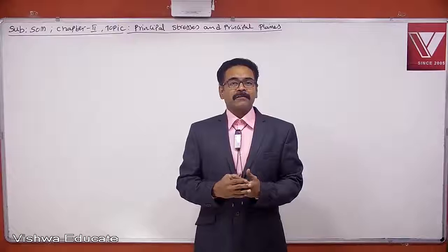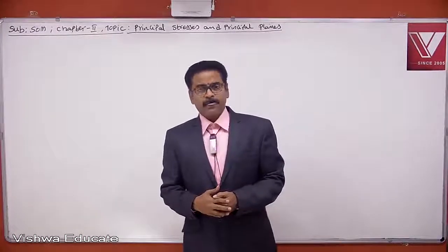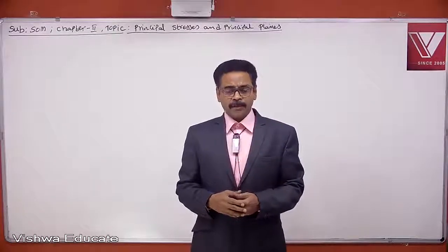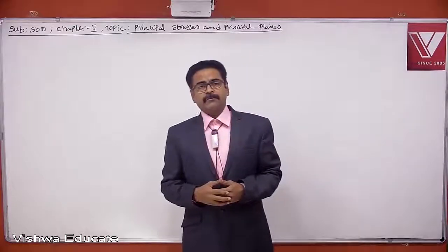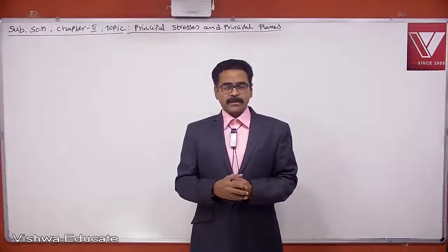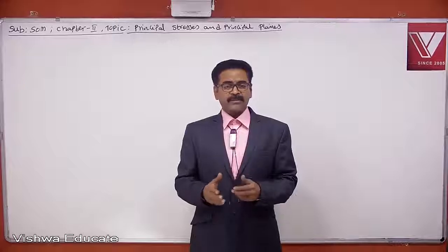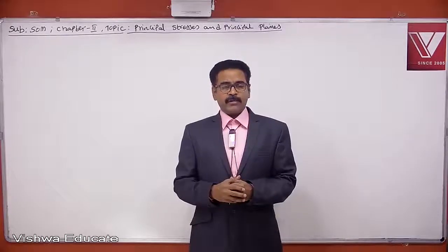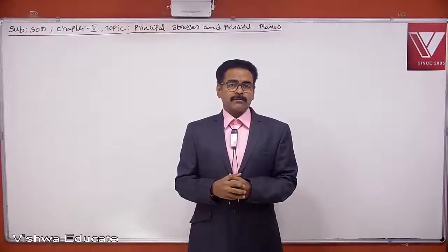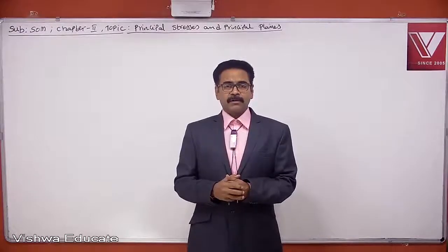Welcome back to another session of Strength of Materials. In this session, we are going to deal with principal stresses and principal planes. First we derive the formula for principal planes and the formula for principal stresses. Thereafter, we are going to derive a formula for maximum shear and a formula for shear planes. In this way, we move, right? So first let us try to derive a formula for major principal stress and minor principal stress.